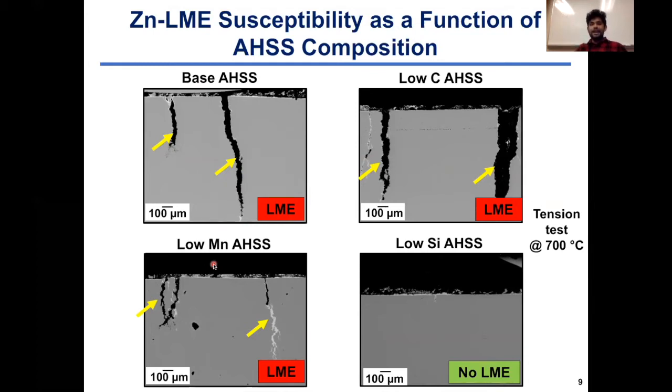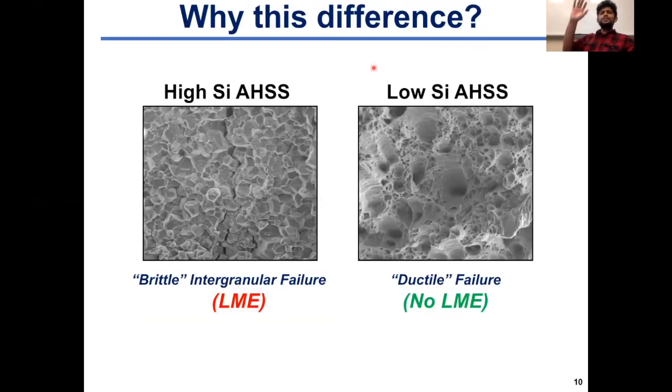On the other hand, the low silicon AHSS has little to no cracking. So we instantly understood that the silicon content of an AHSS independently influences LME susceptibility. Now, this is so interesting.